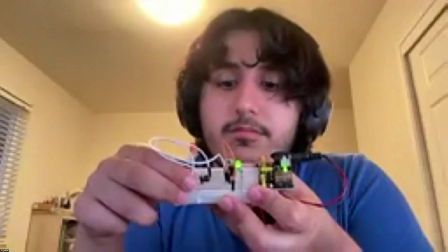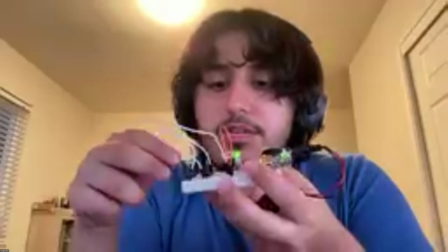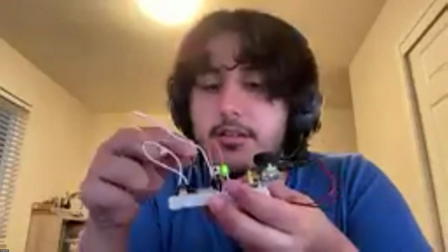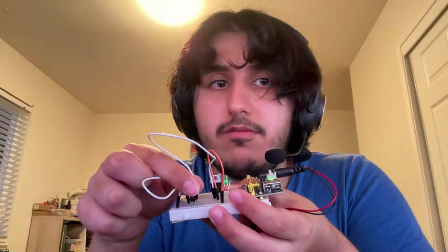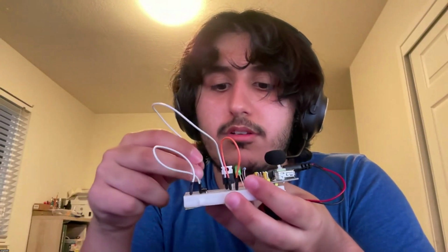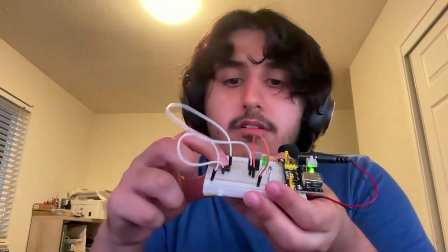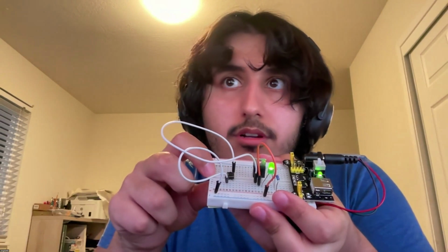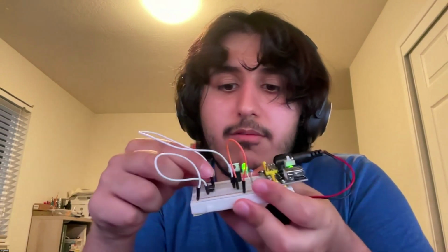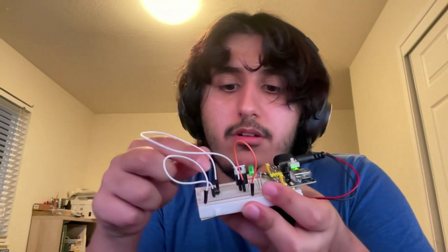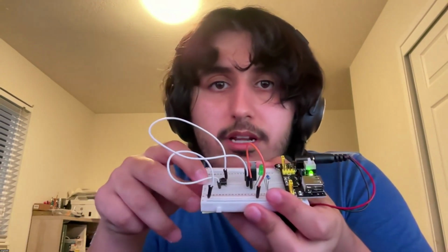Ground the gate. What do I do? Apply a negative voltage to the gate. Right. So if I go here and put it in a negative, right, it turns off. So again, now I turn it off, right? And I press my button, bam, it turns on, right? And if I want to turn it off, I have to physically put it there. Now, anybody have any questions about this?